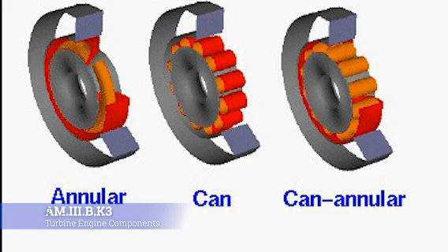All right, now there are four types of combustion chambers that you will run into. First off is the one we've been talking about, the can. So the flame basically resides inside of that can and then moves backwards into the turbine section. Now the can annular has a shroud that effectively connects all of the cans, for lack of a better term, and that allows the flames to spread out more evenly across the cans before proceeding aft into the turbine section. The annular just bypasses the cans altogether and fires it off.